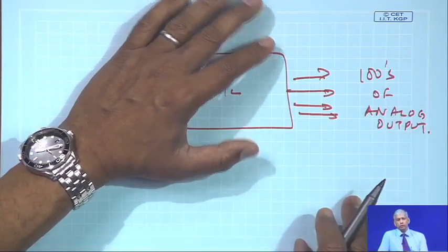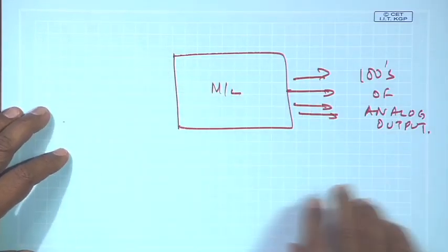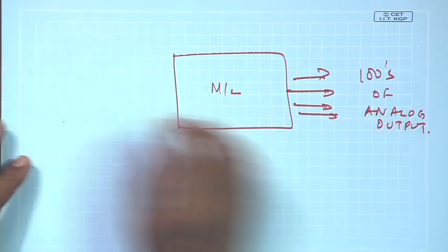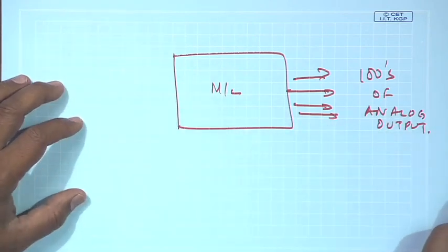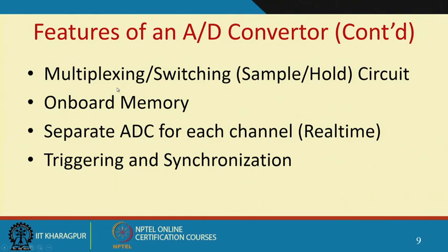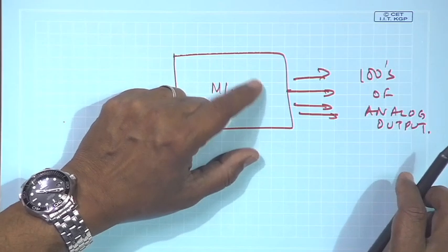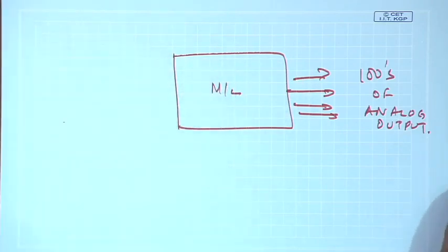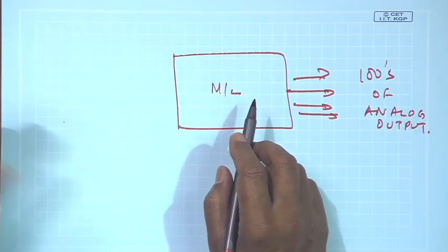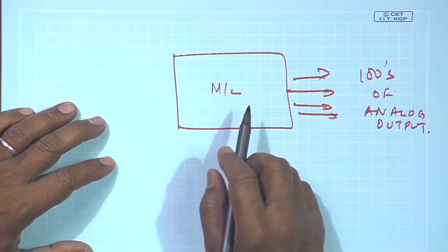Later on, when we talk about wireless data acquisition, you will see how this signal can be transported through Wi-Fi to another device, and what the limitations of signal transmission over the Wi-Fi frequency range are. Sometimes when you have one A to D converter but there are many inputs, we can have an analog or a digital switching circuit, which is known as multiplexing.